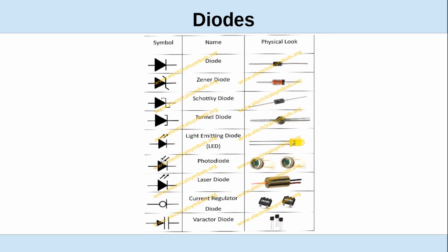So we have the light going into it, and they have a little window in the case so that light can get to the semiconductor wafer. It actually turns out that all diodes are photosensitive. They discovered that, and they can enhance these so they're more sensitive. But if you put a regular diode in a clear case, it would be affected by light.